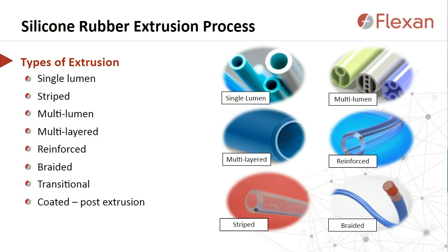Multi-layered extrusions can provide another way to prevent contact with inner or outer surfaces and also add reinforcement. Reinforced extrusions are extrusions that utilize a design element or even a separate material to not only stabilize tubing, but ensure lumen integrity in more challenging applications. This might be helpful in an application where tubing is tightly coiled into equipment, where kinking could be detrimental to the function. Ribbing can be created in the outer wall of the tube, and/or wires or thermoplastic rods can be embedded into the walls to prevent this.